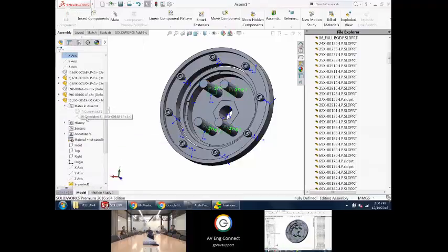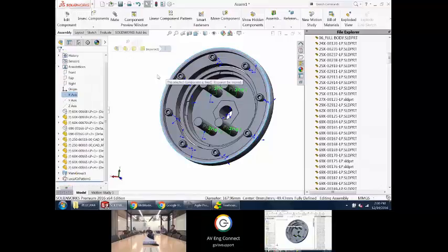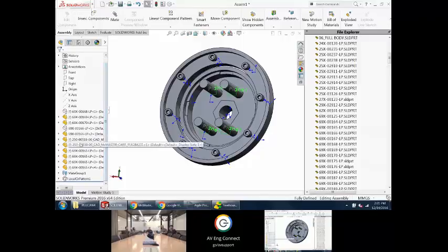What that does is it suppresses all the mates that are in there and just has it, boom, at XYZ location. So now it made it easier for SolidWorks to do it rather than, oh, it's mated here and concentric and a lock. It's just there. But if you change some part, it's going to be really bad. Like if you change the diameter of that disc, those parts will stay in place, and the mates want to blow up because they're suppressed, or they shouldn't. But yeah, you're right that doing a fix like that can be problematic if there are changes still going on.